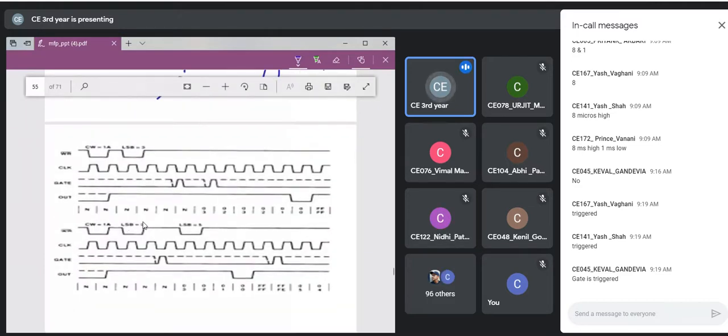So here you can see, suppose I have triggered the gate. According to that, the countdown started. But in between, the gate was triggered again. So in the next clock cycle, the count is reloaded, though the previous one was not completed. So if you trigger before completion, then definitely it will be restarted. Only in mode 2 will it complete the previous one. Otherwise, as soon as you update it, the counter will get updated.